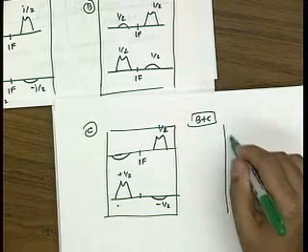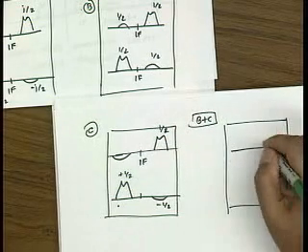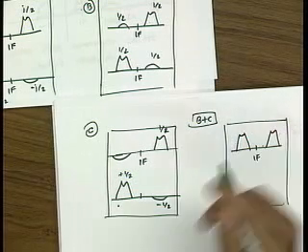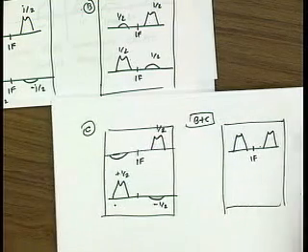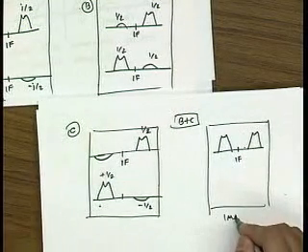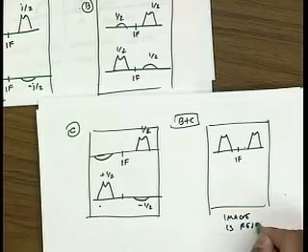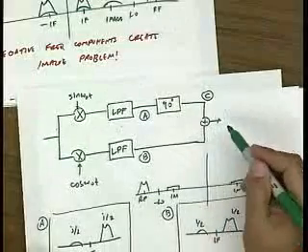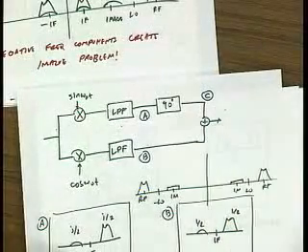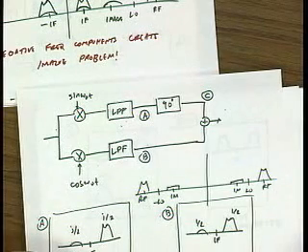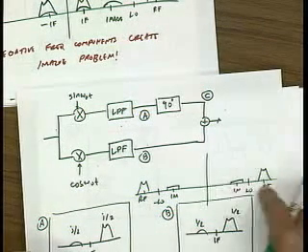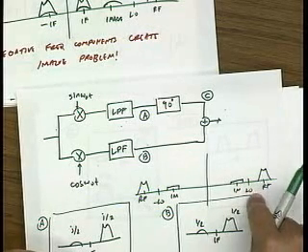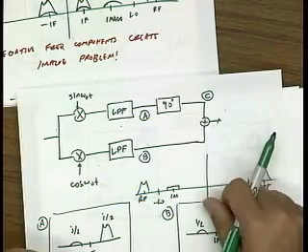So what I end up with is basically exactly what I want. It's my signal which gets down converted, and my image gets rejected. And you can easily verify that instead of adding these two signals, if I had subtracted, the image would have made it through and the signal would have gotten rejected. And of course, which one is your image and which one is your RF is kind of arbitrary. It's whatever you like. Remember, I can either inject my LO above or below the signal. Okay?